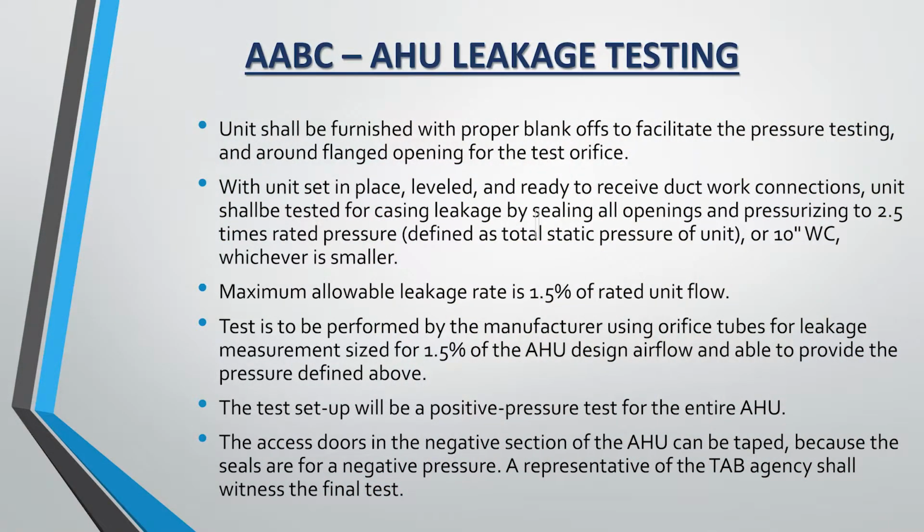Do we do that pressure testing on those casings after all that's done or before? And that's something you need to take up with your owners, commissioning agents, and the team to say, okay, we do all this before, and then the owner gets in there at acceptance and his hair's getting blown sideways because air's blowing out of this junction box or out of the air handling unit where the VFD's hooked up. He's not going to be too happy. Like, well, what'd you guys do to my unit? So very, very, very important to make a coordination effort beforehand to figure out how you're going to test those, when you're going to test them.